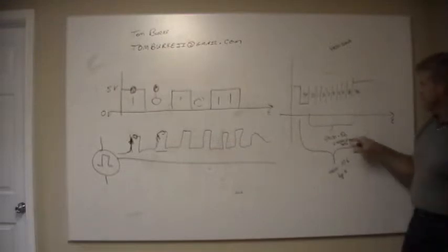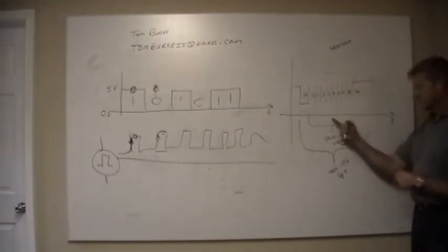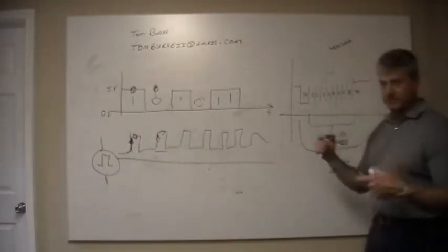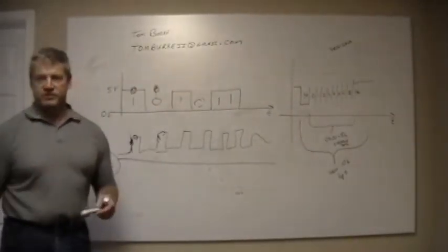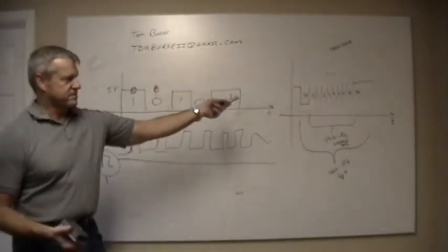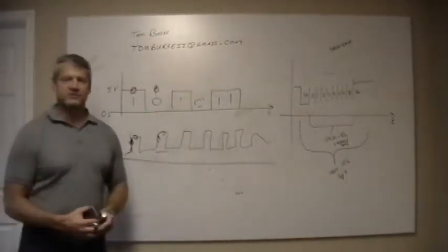I can't do that math in my head either. I'm getting less than 48,000 bits per second of data down. That's the difference between baud and bits per second. But we use them interchangeably most of the time because that's less than a 10% overhead. Actually, that's a 20% overhead for that one, so it's considerable.